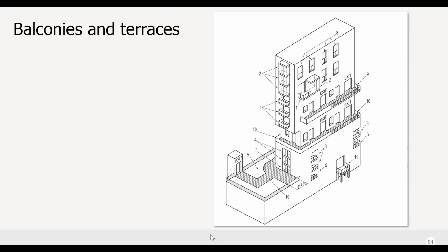In sections 15.1 and 15.2 of the standard, drainage of balconies and small terraces, we state the design of balconies should incorporate some form of controlled drainage to prevent water ingress into the building, unsightly detrimental staining of the building and or nuisance to people or damage to landscaping below.